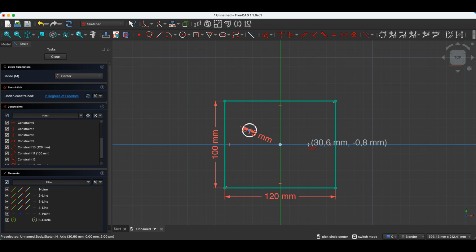As you can notice, in this case, a coincidence symbol appears that binds a point to a line. If I hover over a point, a coincidence constraint symbol appears that binds a point to a point. It is one and the same constraint, it just has different symbols. If we want to constrain a point to a point, something like an X appears, and if we want to constrain a point to a line, a point lying on an arc appears. In this case, we happen to want to apply this constraint.